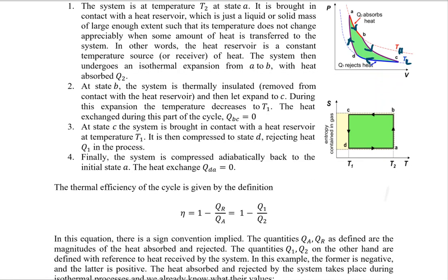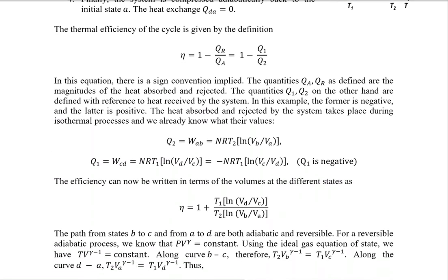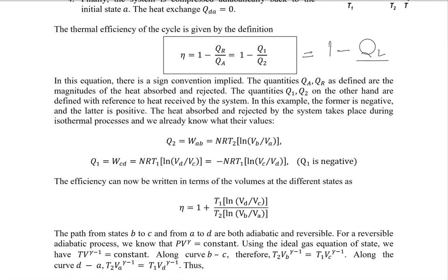So that means the thermal efficiency of the cycle is equal to 1 minus TL by TH, which we have derived in a previous lecture, or 1 minus q rejected by q accepted. If you are familiar with 1 minus QL, which is q lost, by QH, which is actually the high temperature reservoir heat which is absorbed.